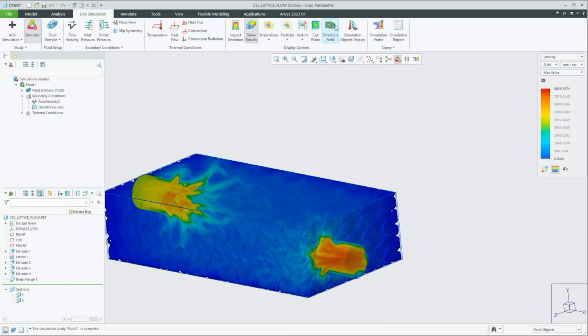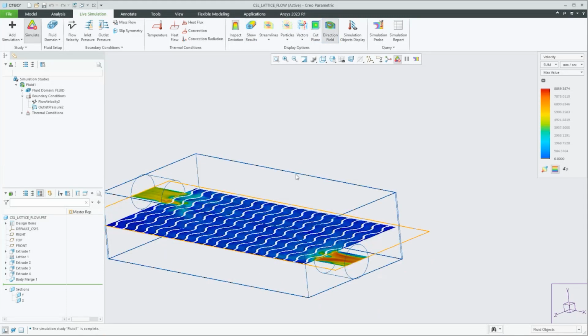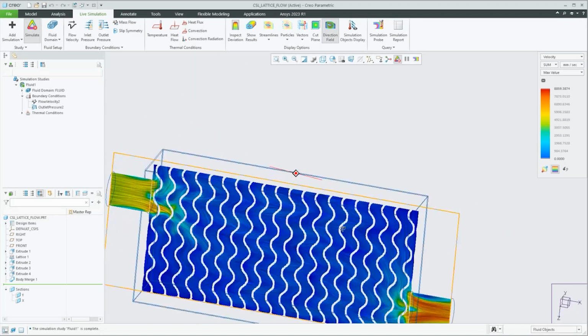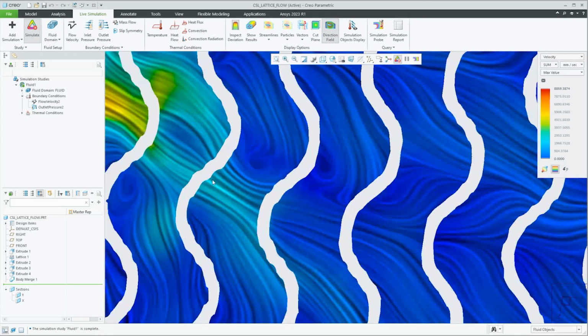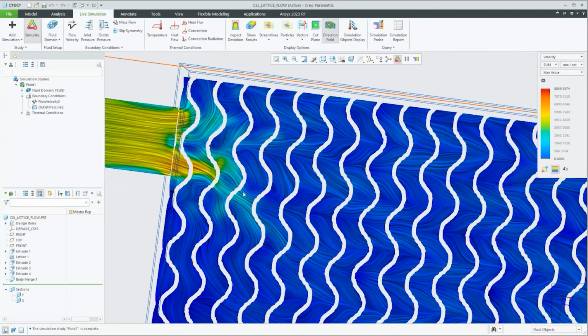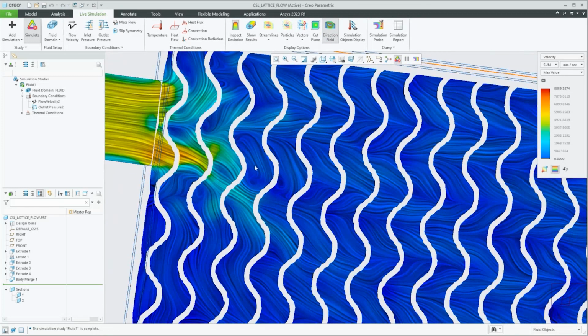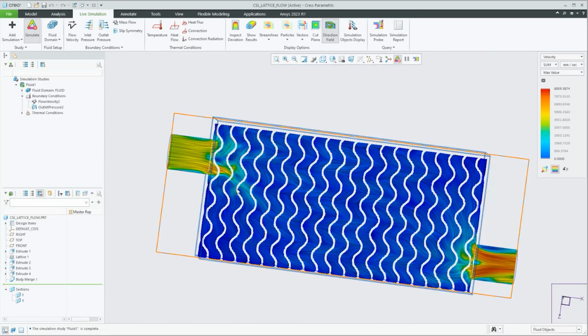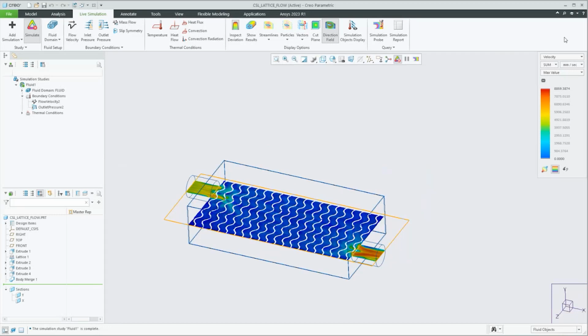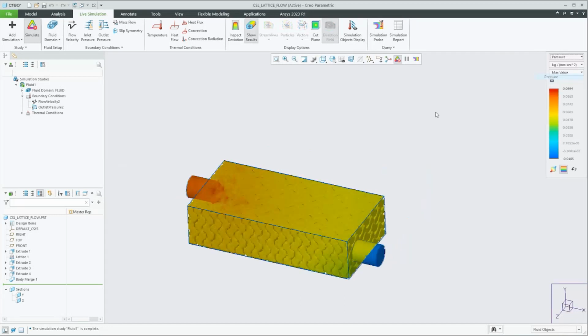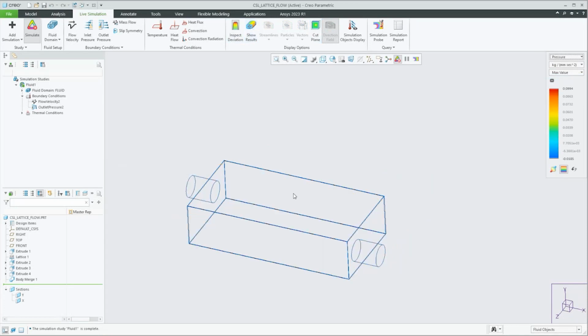And I can also do what they call a direction field analysis. In CFD terminology, this is what's known as a line integral convolution. We can see the flow patterns here, and particularly where recirculation regions are occurring. Incidentally, at the moment I'm looking at the velocity, but I can also look at other quantities like pressure and so on.